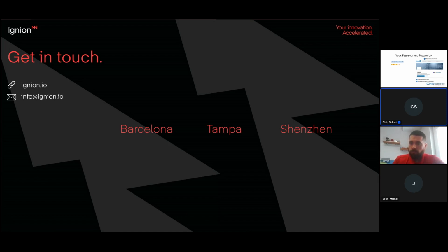We have a question from Jean-Louis. Is the AI tool you have also able to design antennas for ultra wideband kind of signals? Yes, the Antenna Intelligence Cloud tool is able to cover from 450 MHz up to 10.6 GHz, including also ultra wideband. For specific topics related to ultra wideband, for example, I cannot recall right now, fidelity factor, group delay, and so on, it is not included in the Antenna Intelligence Cloud, but you can request our technical team to run a specific simulation for you, and then all of these considerations are included in an electromagnetic simulation service. So yes, ultra wideband is included also.